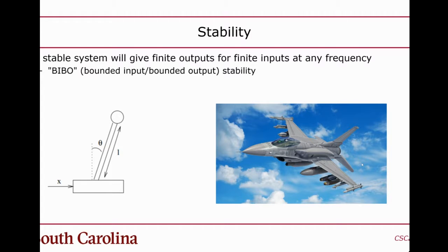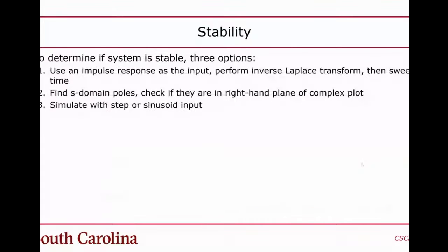And so they have a controller in there that sits between the pilot and the plane. The pilot basically gives the controller a set point, and then the controller is constantly making small adjustments to all the control surfaces to keep the plane flying straight, or to do what the pilot wants it to do, following the set point. So that plane is unstable the way the airframe and control surfaces are designed. It has a controller, and they did that to make it more maneuverable.